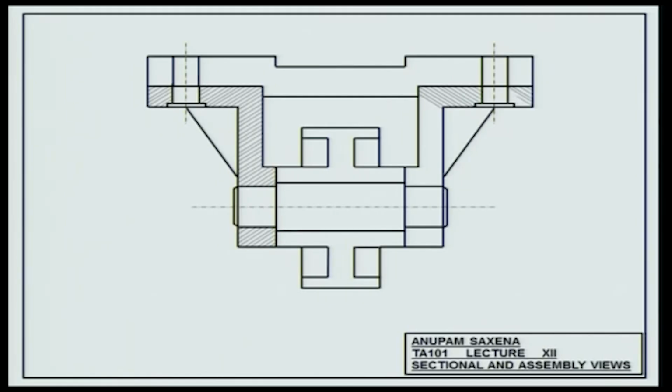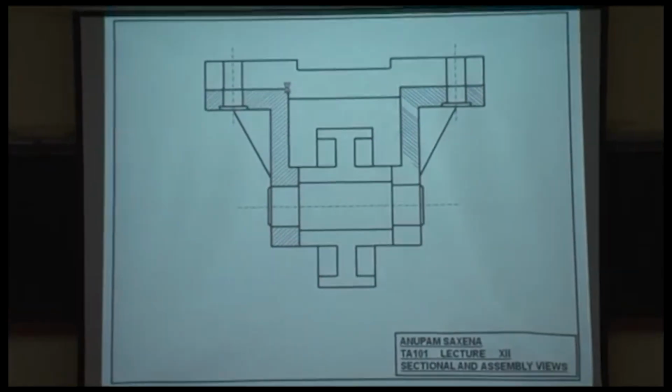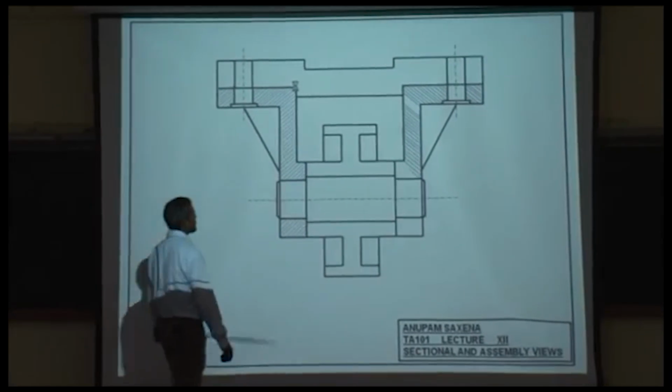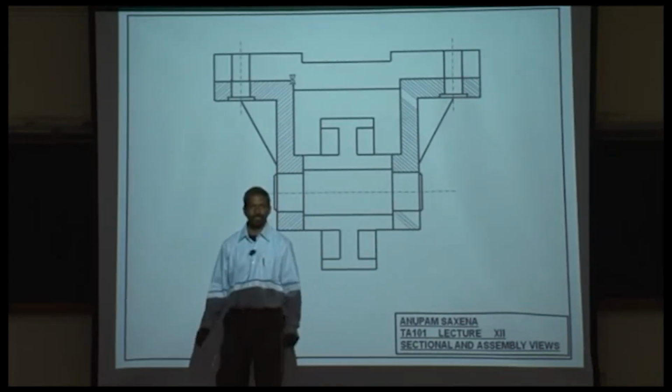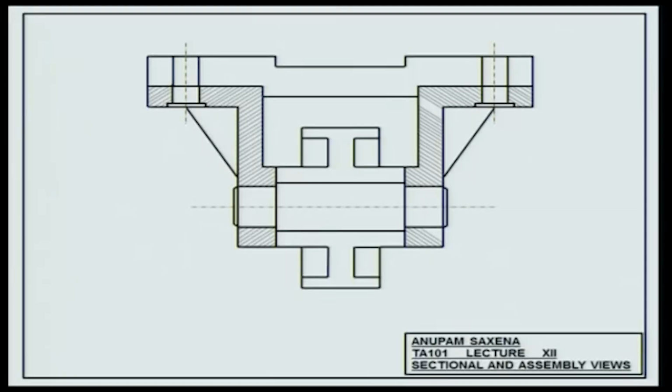The left bracket positive 45 degrees, the right bracket negative 45 degrees or 135 degrees. You would want to avoid something like this in your diagram. It needs to be perfect. And then you start hatching the base plate. Again 45 degrees, but with a larger spacing between the hash lines.